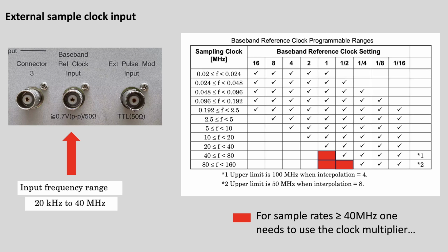But then again, you might not have exactly those signal pulses that you're looking for. So at these high speeds, above 40 megahertz, this is something that you have to take into account when you use the device. So with this workaround you can kind of get there, but again, I don't really see why a clock out or word out, if you wish, for the whole word in case of a more complex constellation, or symbol out if you want to call it, is not available on the device.